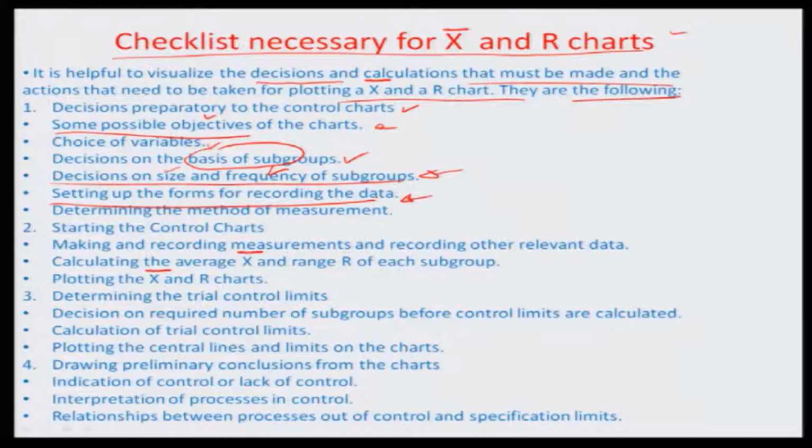And then obviously, you have to determine the method of measurement, whether it is just a vernier caliper which you are inserting in that slot for measurement, or maybe a gauge that you have built, which you align and see whether a gauge of a certain value is going into that slot width. So, many options like these are available.